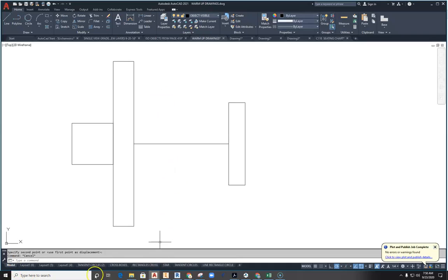Now, the next step is that we're going to draw lines from point to point. This is like playing connect the dots. Grab my line tool. I go from this endpoint to this endpoint. Click. Right click. Hit enter or hit escape. Either one works to finish that command. Endpoint to endpoint. Hit escape and command.